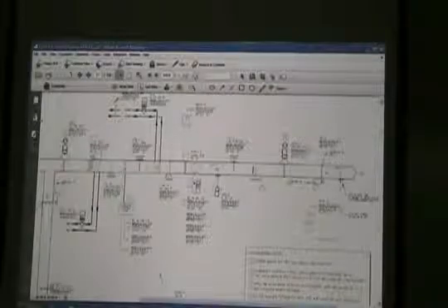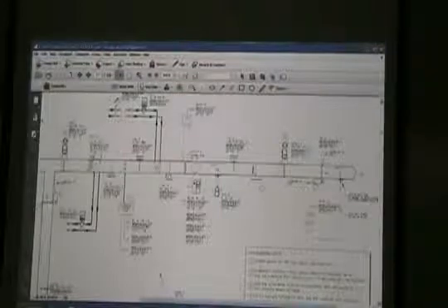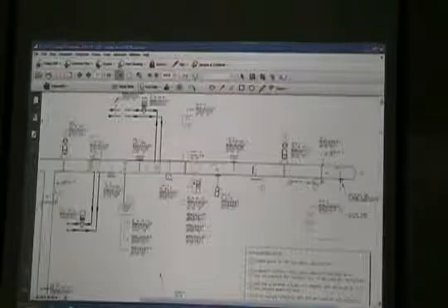Control band, set point increment values, set point decrement values, and frequencies shall be adjusted to maintain minimum static pressure and supply air temperature optimization of stable system control. Maximum comfort control. Change the set point of the control loops stabilized within 2% set point. That's programming language, and has to do with PID loops, how quickly you change them.